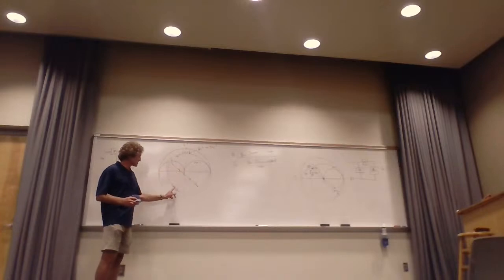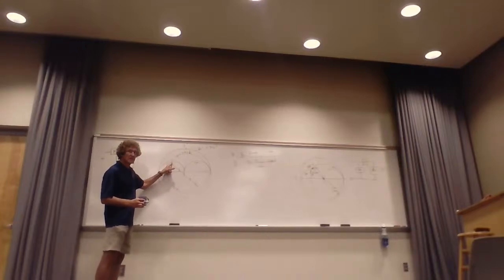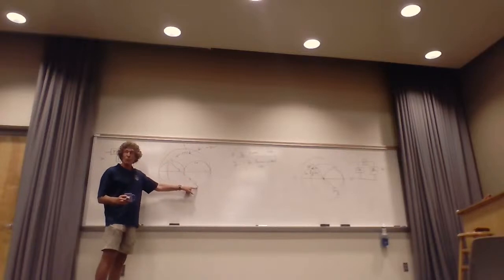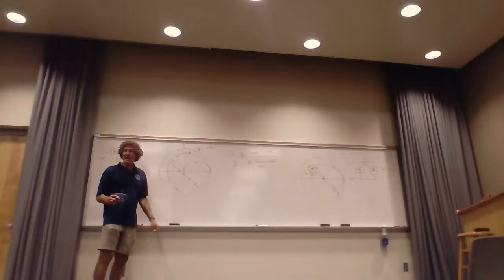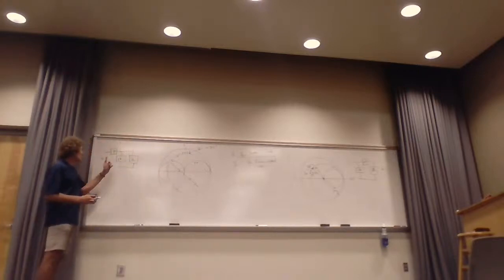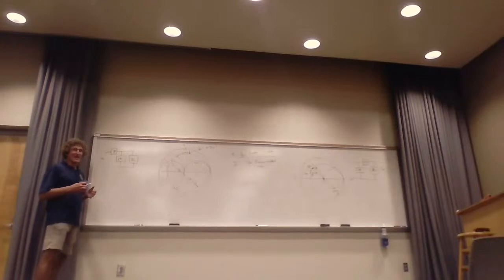So if we go to the admittance domain and add something in parallel, whatever this corresponds to would be the element in parallel, that jB. Then actually you'd want to move to here if you want an inductor in series. Now I'm in the admittance domain, I go back to the impedance, I have 1 plus j or 1 minus j something, and I add a series inductor. But this is important, the order is critical. If you put this first, then it's not matched at all. As a matter of fact, it's a disaster.